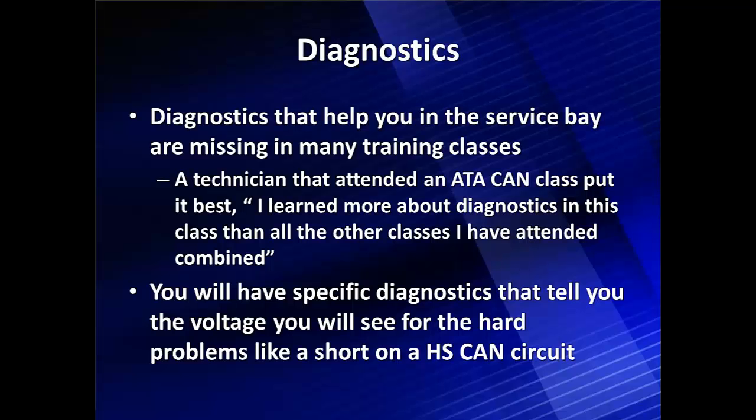A technician that recently attended an ATA training class put it best. I learned more about diagnostics in this class than all the other classes I've attended combined. You'll have specific diagnostics that tell you the voltage you will see on hard faults like shorts on high-speed CAN and how to isolate them on manufacturer-specific diagrams.